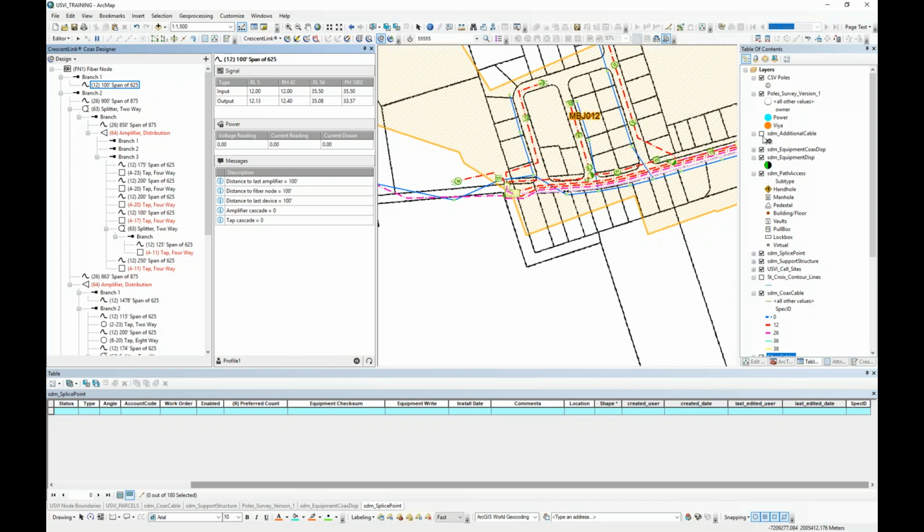I don't necessarily want to tell it what that point is. I just wanted to run a report to see how many of those points are within 5 feet of this, or within 15 feet of this cable run. That you could do, yes. Your point exists, yes, you can tell it. You want to say, I want to see everything within 20 feet of this splice point. Something like that, yes, you can do that. No problem. Within 200 feet, within 500 feet. Yeah, you can do that.